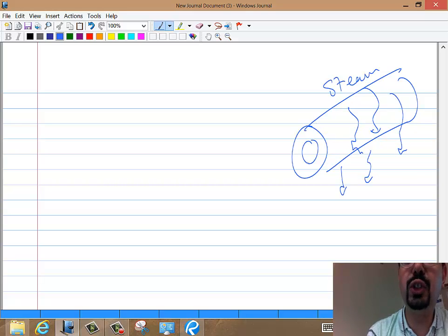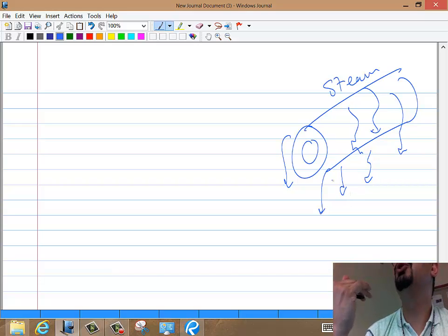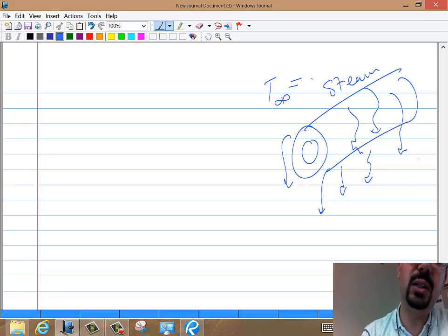So we have a whole chapter for boiling and condensation. But you should basically know that if you have condensation, it would happen at the same temperature. So the steam would be condensing and turning into liquid, from vapor to liquid, while both the vapor and the liquid are sitting at the same temperature. So T infinity is 120 degrees.